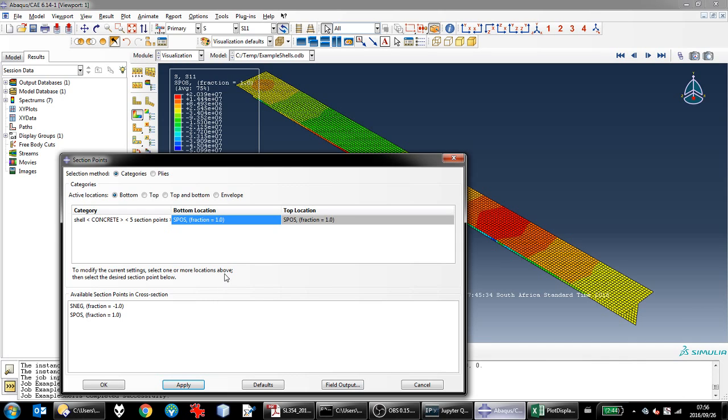You have to remember that the shell element stress varies in terms of its thickness. So if you've got quite a thick shell element, it's reasonable to expect that there's quite a different stress on the bottom surface versus the top surface. So what I've selected here is to plot the bottom again. Oh sorry, it doesn't want to. You have to pick it here. It's the negative surface, apply. It's much lower. We're looking at only 16 megapascals.